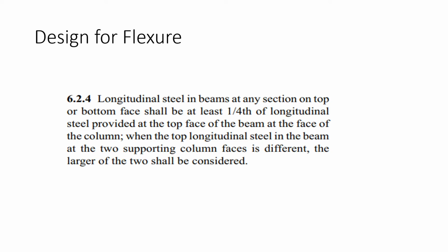There are two other clauses that I am going to tell you, theoretically, and their meaning. Longitudinal steel in a beam at any section on top or bottom face shall be at least one-fourth of the longitudinal steel provided at the top face of the beam at the face of the column. Let me explain.